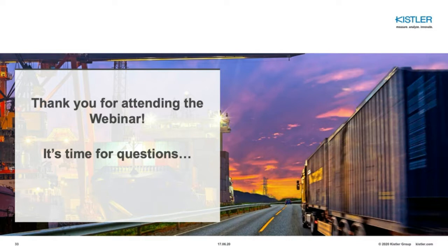So basically you rent a truck, you do the static weighing of the truck, and then you do a couple of runs over the WIM site, and therefore get the calibration values calculated by a WIM system, and therefore then compensate some of these effects. The KiTraffic Digital is calibrated in the same way, so you also do the truck runs with known weights.